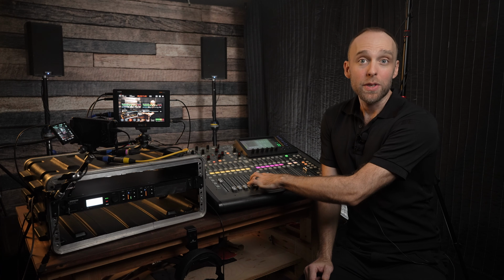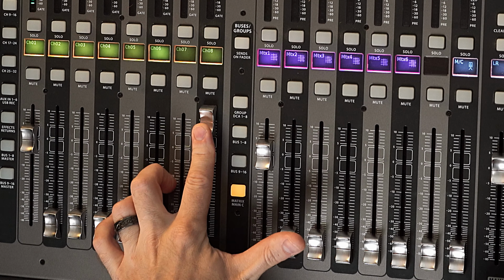It doesn't automatically boost anything to line level. The equipment does what you tell it to do. Faders can boost the signal a bit if you're above that 0 mark, but usually by only about 10 dB more. But they can only control what you send them from upstream of that particular point. Faders and console outputs don't normalize anything or automatically set your outputs to any level. They do what you tell them to do. If they're at 0, they simply pass a signal that you're sending to them. And this is why you have to gain and set levels visually with your audio meters.